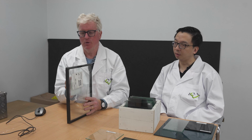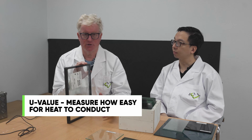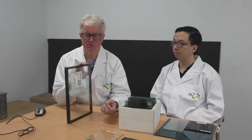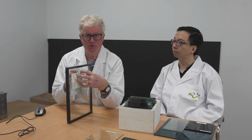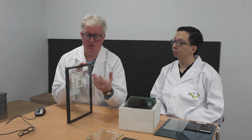The U value is, like with any other opaque material, the conductance or conductivity of the glazing system or the material system. And that relates to the thermal conductivity of the material of glass, in this case, itself, and the insulating aspect of the cavity.